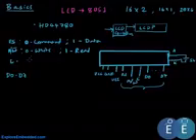Now enable is something similar to a latch or a gating pulse. We need to send a high to low pulse anytime we do any of these operations. Whenever we do a command read or command write, or data read or data write, we send an enable pulse. Now what is the difference between command and data?